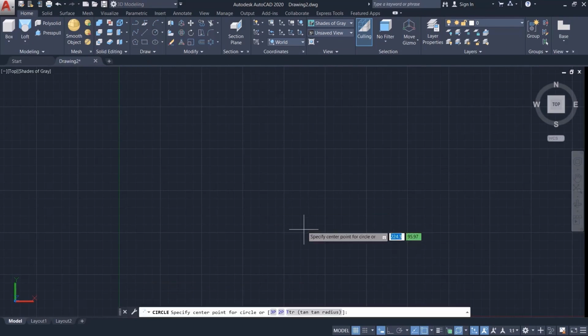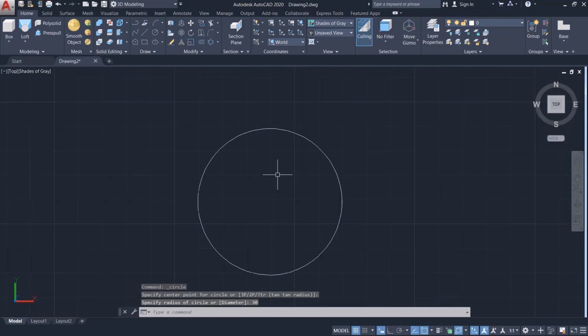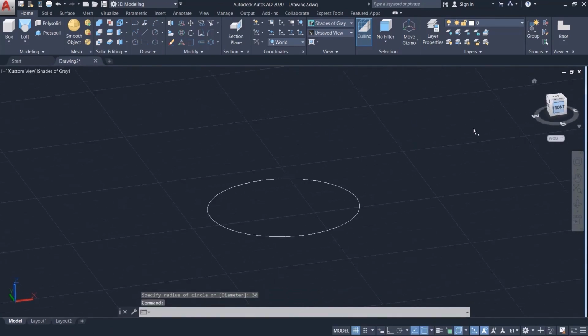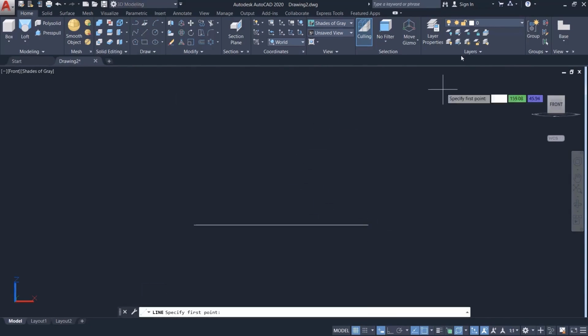The diameter of the bottom circle of this tower section, this structure section, is 60 meters, so we enter the number 30 like this, and then in the front view, we need to draw some guidelines. Now, for example, from the side of this shape, we can actually draw the hyperboloid element of our shape, so that when we draw the elevations, the center of this 8 is also clear.